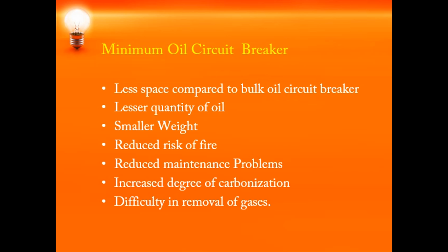The outer part is made of porcelain. The advantages of this minimum oil circuit breaker: first, it requires a lesser quantity of oil. The space required is also very small. It is lighter in weight compared to the bulk oil type. It has a reduced risk of fire and less maintenance work compared to bulk oil circuit breakers.